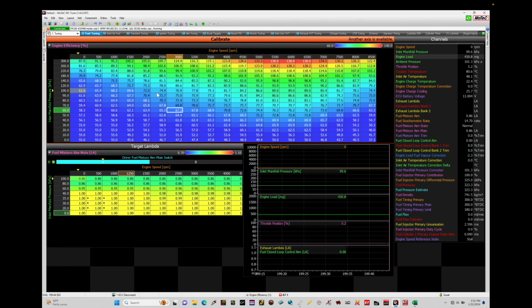So what we'll find is that if we enter in bad injector data, we'll essentially be able to fix it by going in and skewing our VE values up. Now, in the last tutorial we talked about spotting proper VE values in our VE table utilizing our Excel calculator. We're going to jump back into that calculator in this tutorial and discuss how we can use that as a sanity check against the VE values to determine if we have proper injector data or not, if we're setting this up in the manual configuration.